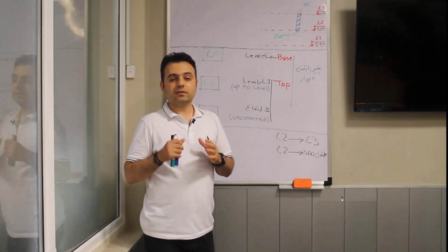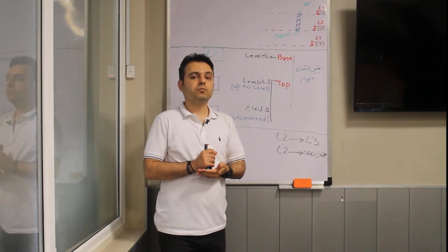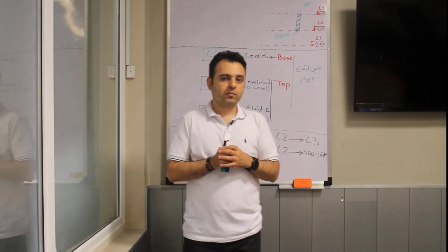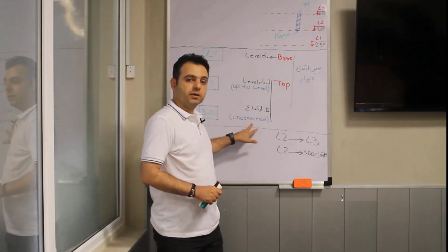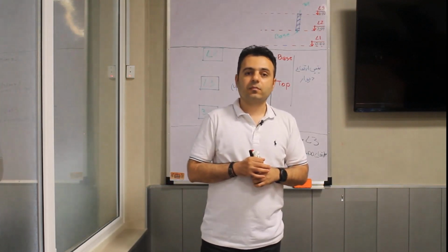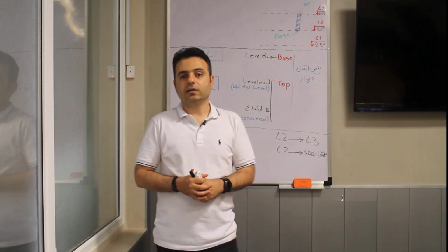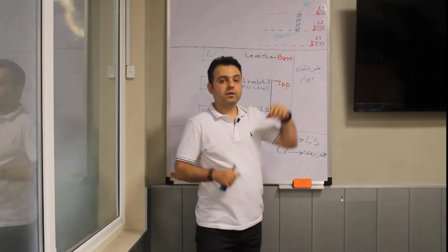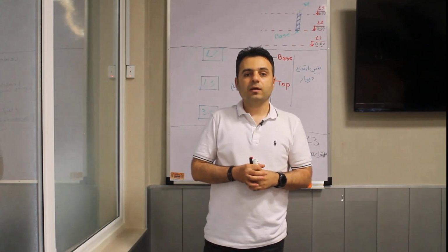Now the subject is the top of the wall. In 95% of the walls of a project, we use one of these, and which one is that and why? Well, think about it. Is it up to level or unconnected? And why? Is there anything in your mind? Well, if your answer is up to level, well, it's completely right. It means that we always connect the top of the walls to the levels. But why do we do that?